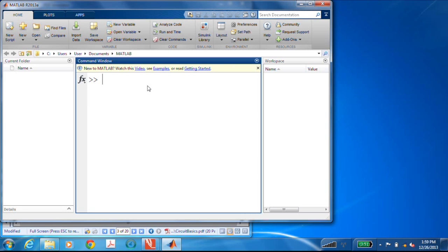Alright, so what I'll do is I'll define R, my resistance, as being 100,000 ohms, and my capacitance as being 1 microfarad. Now if I look at my time constant, R times C, I see that it's 0.1, and we know that the units of that are 0.1 seconds. Let's just create a quick transfer function of it.